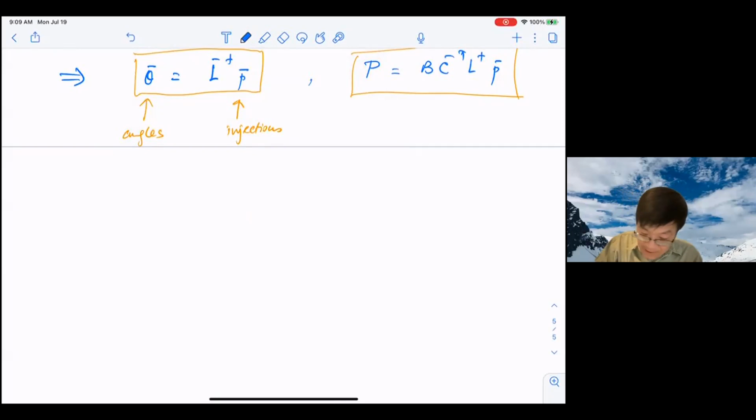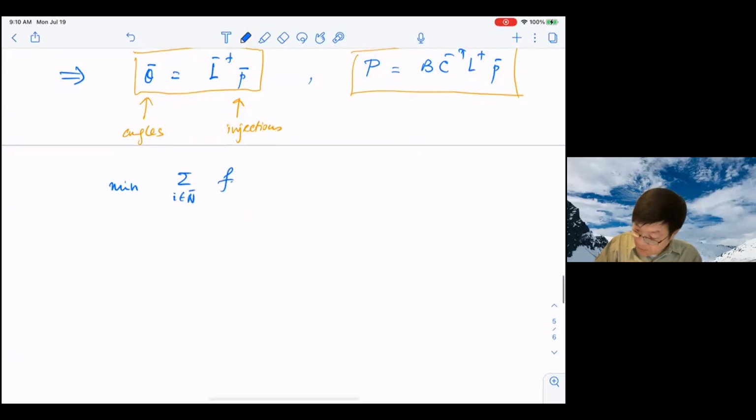And you can formulate this as typically you want to minimize the sum over the nodes of Fi of Pi. So Pi is the real power injection. Typically, Pis represent generations. But in the future, it may also include loads, flexible loads. Right? And therefore, generically, we can think of this as a controllable injection Pi at each node i. They can be generation, they can be load, they can be prosumers. If the injection at node i is not controllable, is fixed given load, then we can do this.